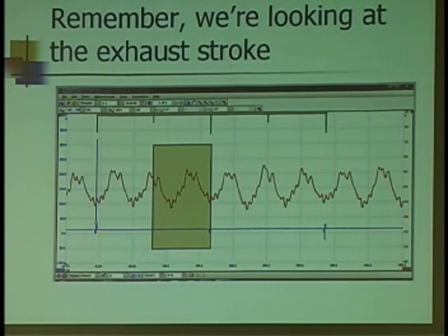Now the First Look comes with a little chart that tells you if you have a 4-cylinder, you move to the left 2. If it's a 6-cylinder, you move 3, whatever. I can never remember that. So what I do is I take a capture and put it in my Windows Paint program, and I add some reference lines of my own so I can say this is 0, 180, 360, you get it, 720.